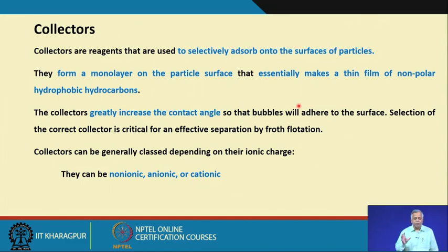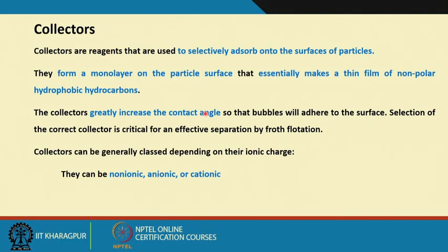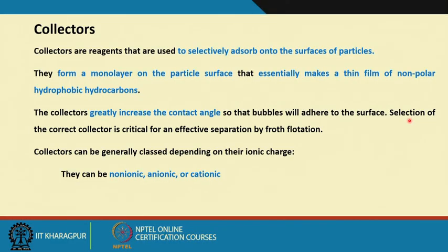That means, when the contact angle increases, the surface becomes more hydrophobic and the bubbles should adhere to the surfaces of these particles. Once the bubble gets adhered to the surface of these particles, by its natural tendency it will try to go up and carry my particle. That is the very purpose of this flotation process.